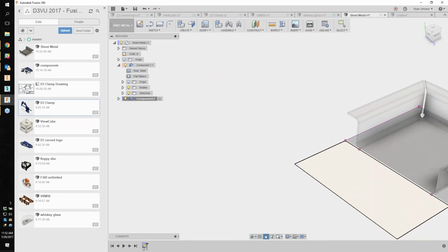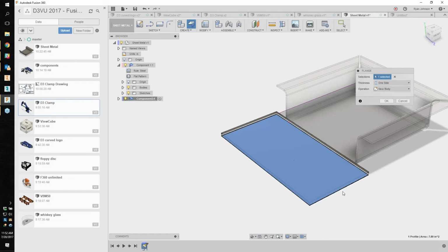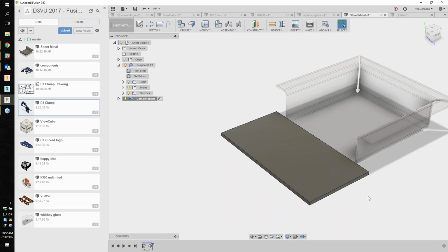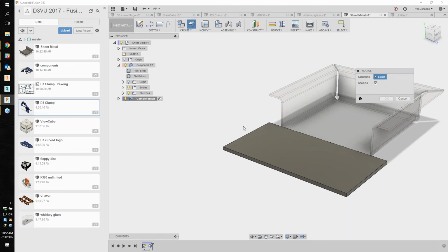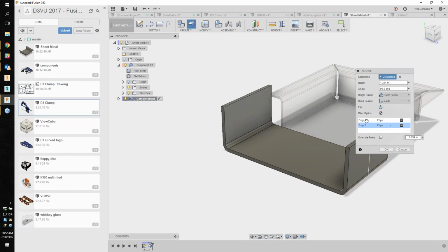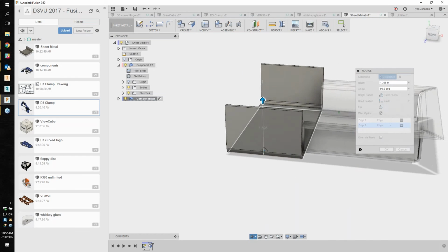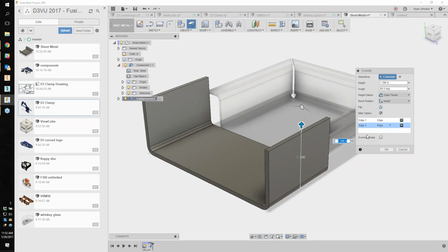Inside of Fusion 360 sheet metal tool, we don't have a long list of tools. We don't have a flange, a face, a contour flange. Instead, everything is this single flange tool. It's pretty cool. Depending on what you select, Fusion will decide which operation you're trying to do. If I use the flange tool and I grab an edge, it becomes an edge flange. If I grab the closed profile, it becomes a face.